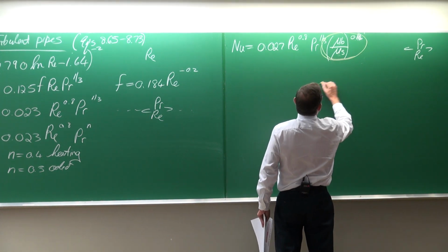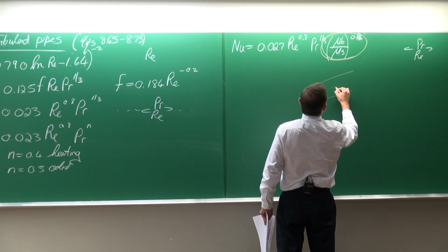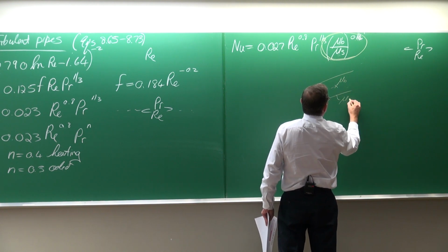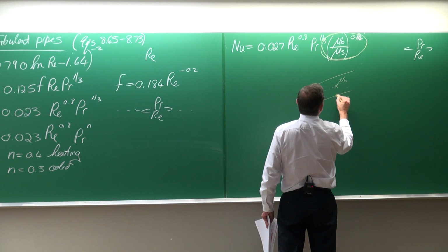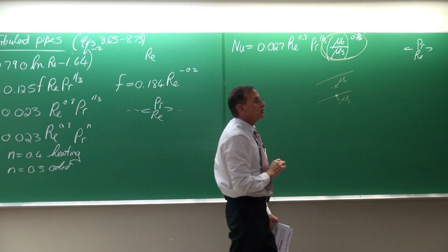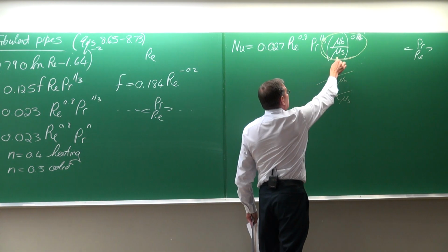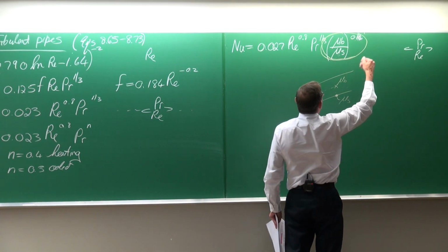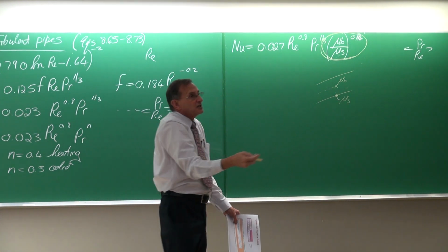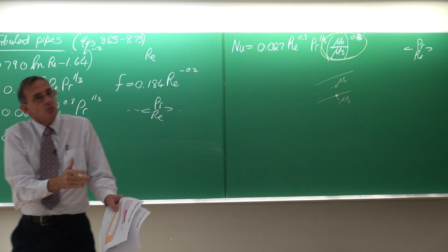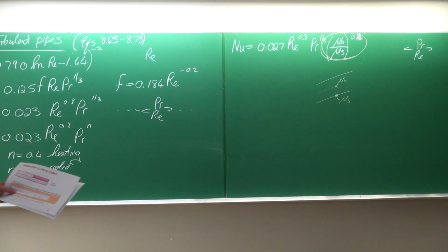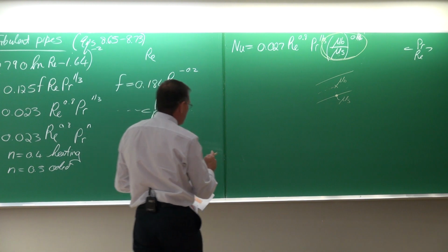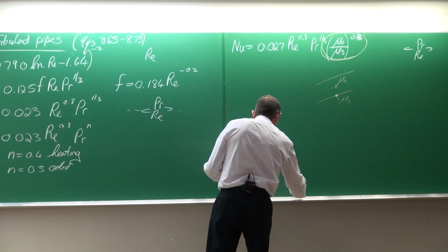What is the difference between these? This is the bulk viscosity, and that would then be the viscosity on the surface. So you need the surface temperature, you need to be able to get the bulk viscosity in, and if that ratio, to the power of 0.14, starts becoming less than 0.9, 0.8, 0.6, then it is very important to take that into consideration. Again, depending on the type of design that you're doing.